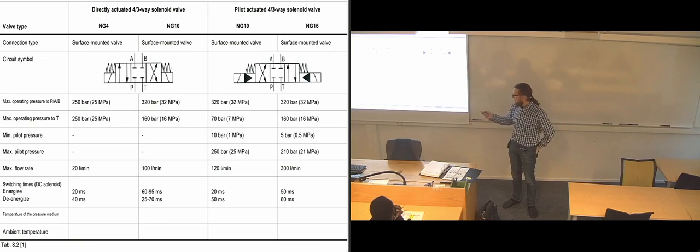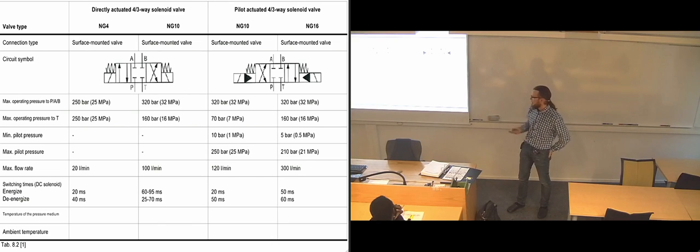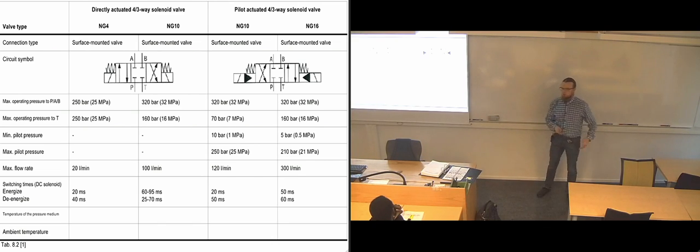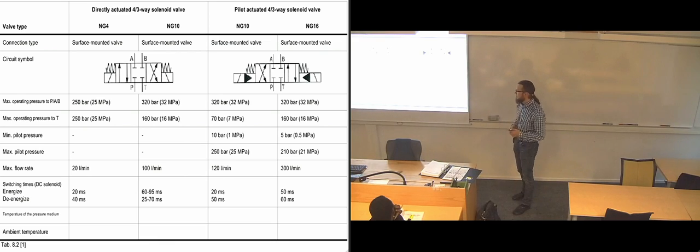And you can see here, it doesn't really take much time to energize them. You have anything from 20 milliseconds up to 95 milliseconds. So it's really, really quick to move these. And you can see for the small one that is directly actuated, there's not really much of a difference between the pilot one and the directly actuated one, even though the pilot one is larger.